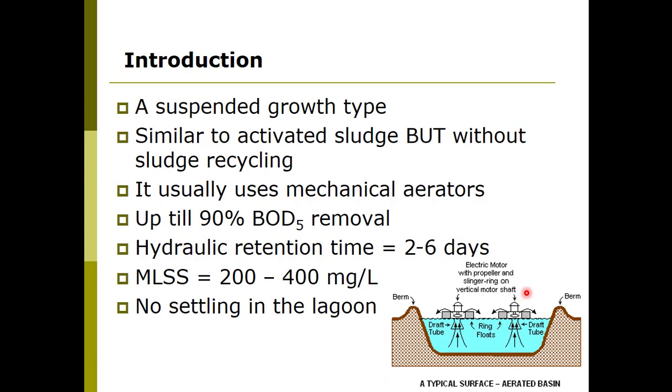In fact, surface aerators, or aeration in general in the aerated lagoons, play two functions. The first function is to provide the required oxygen, the required air for the biological treatment. It also provides the mixing required for the bacteria and the organisms to contact the wastewater components, the organic matter. So it provides the oxygen and the mixing required for the treatment process.